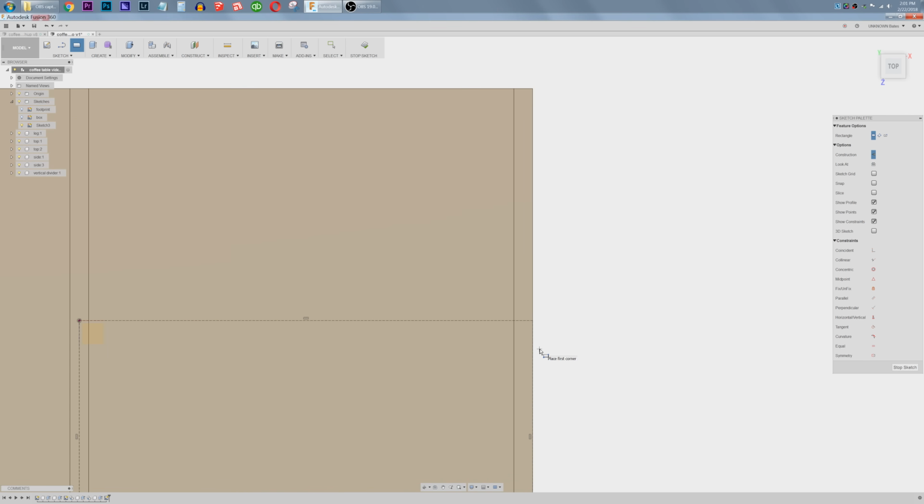Now I'm going to just draw one dovetail. Press escape. Let's see, turn construction off, L for line, and let's just draw one tail from here to here, from here to here. Nothing really matters at this point, from there to there, from there to there. D for dimension, let's just say that this is, I've already established 3 inches will work. I'll just type that in. D for dimension, and from here to here, 75 degrees, that looks appropriate, but these are not identical.